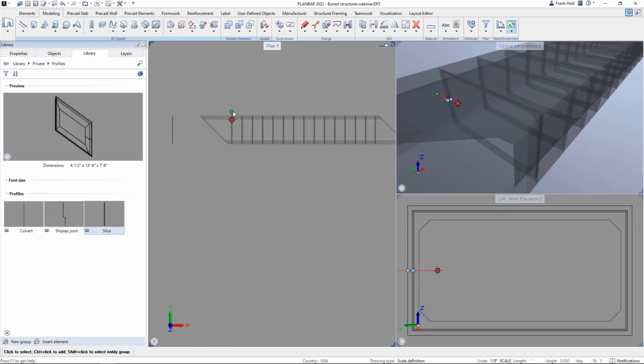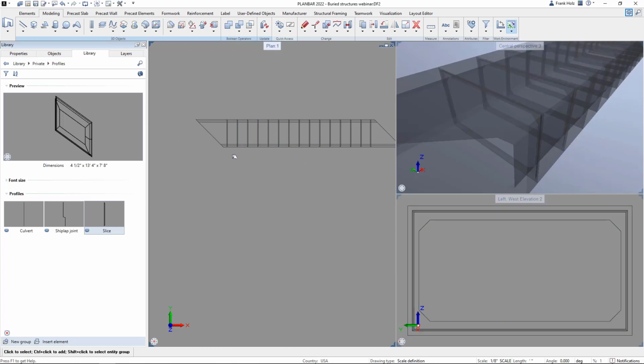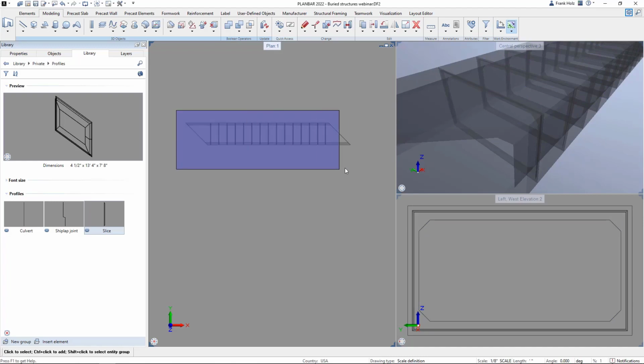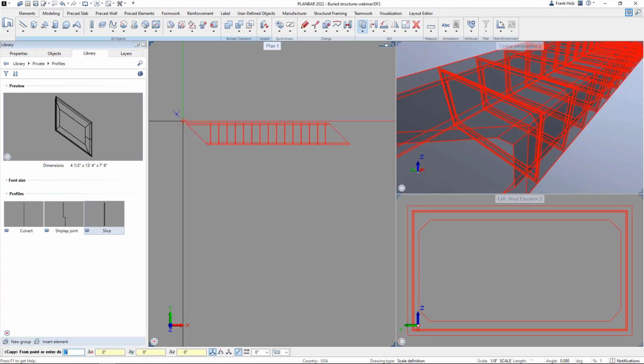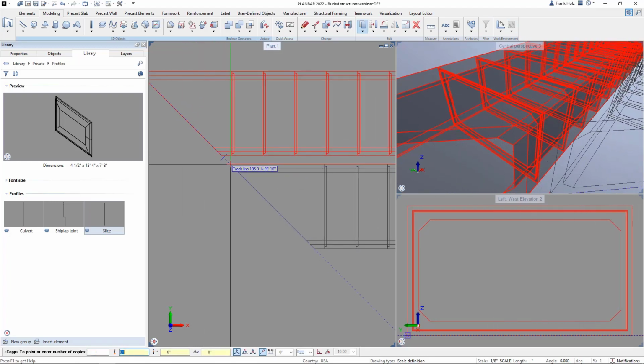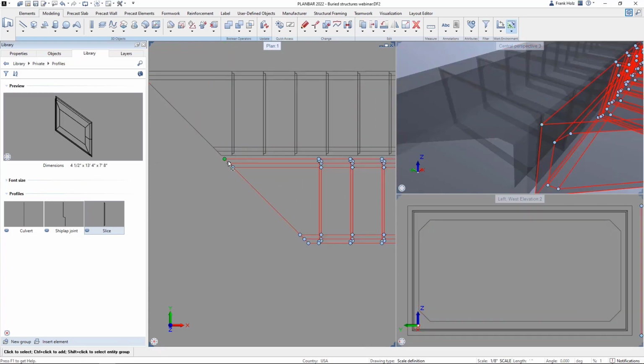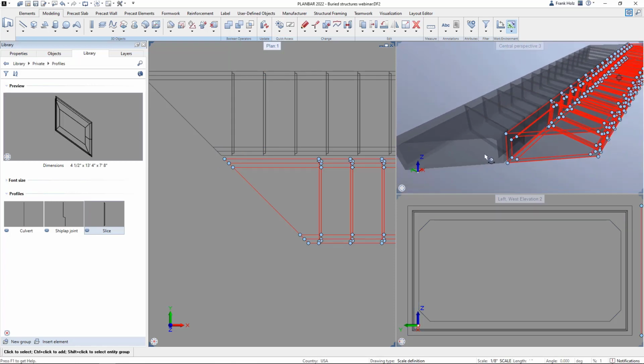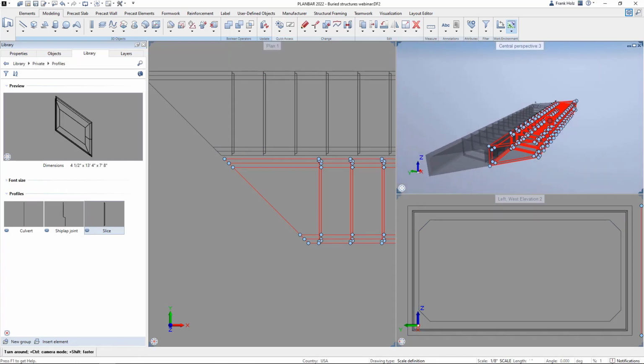Now we may want to add head walls to the skewed ends. We may want to add different openings and whatnot. So we can go down and knife and fork these if we want before we make a copy of it, but I'll just go ahead and make a simple copy right now like we did before. So just track it down at 45. Obviously we'd snap to a specific location, but here I'm just placing it over a little bit to show that we now have our double run box culvert.